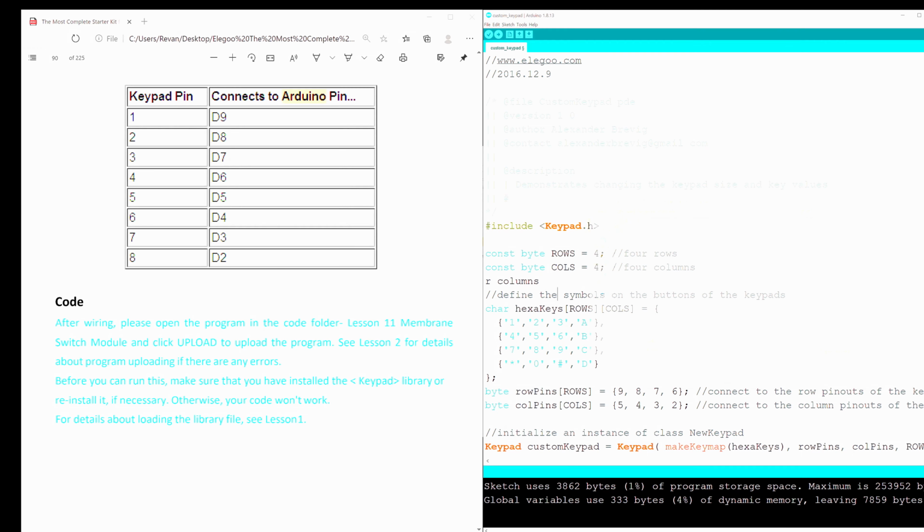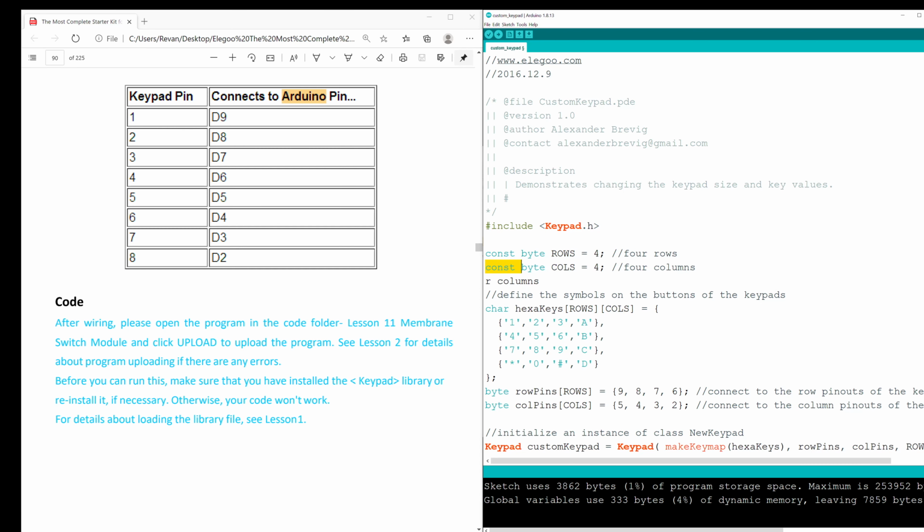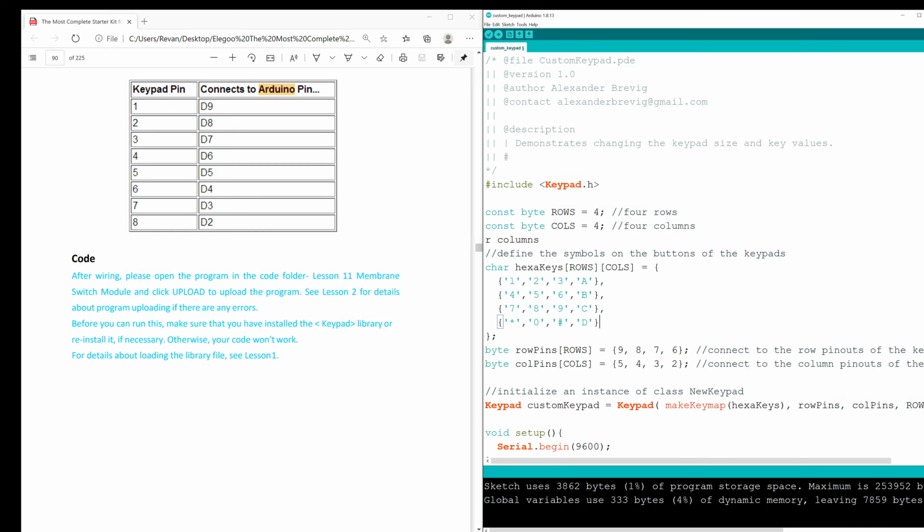Let's keep going. Next, we get to const byte ROWS and const byte COLS. A constant byte stores an 8-bit unsigned number from 0 to 255. This will assign the rows and the columns. Next, it defines the symbols on the buttons of the keypad itself. char hexaKeys[ROWS][COLS] equals brackets. Now this sounds really confusing, but I'm going to try to explain this to the best of my ability. So char means character, hexaKeys just means 16 keys, and now we're going to be defining the symbols on the buttons of the keypad. Well, there's just one keypad in this instance, but...